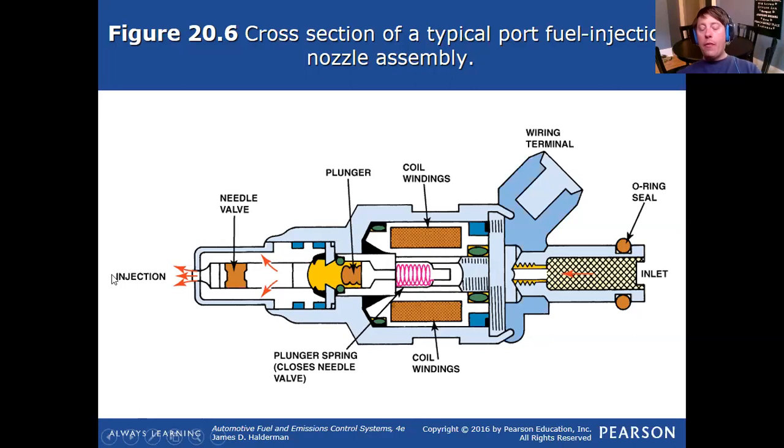So kind of think about a fuel injector as a door. You have fuel on one side of the door and you have nothing on the other side. You have a cylinder. The injector, as it's turned on, is going to momentarily open the door and allow fuel to flow. As the injector is turned off, there's a spring that'll hammer that injector back shut.